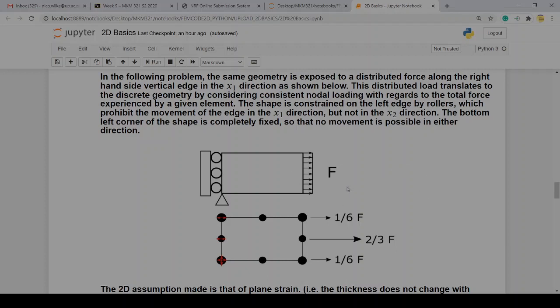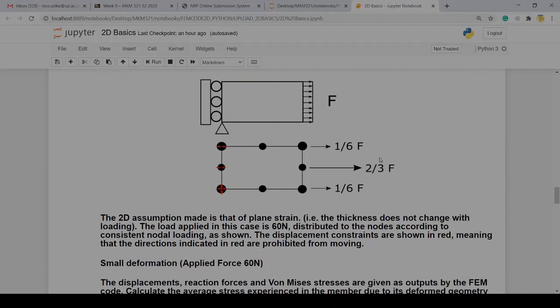Remember, in the body force, we also had that split 1/6, 2/3, 1/6. And so what we learn here is that the body forces in the 1D case and the tractions in this 2D case split the same, because essentially here we have a quadratic response of the function. You substitute the values for psi equals 1 in here, and it's only a function of eta. That function of eta looks exactly the same as a quadratic 1D element. So that is the rationale behind that.